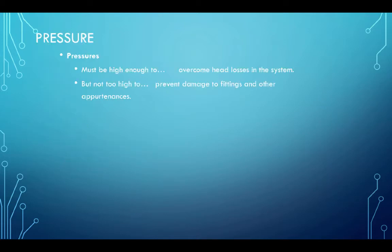Okay, so the pressures have to be high enough to overcome the head losses in the system, as well as provide positive pressure in case there's a breach so that contaminated water can't leak back into a distribution system, but not too high so that we don't damage fittings and other appurtenances.